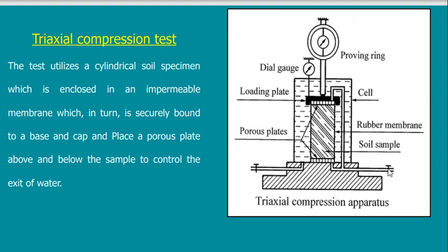If I close this tap, water will not leave. So this tap controls what we said, the permeability. If I close this tap, then it resembles clay with very low permeability, because water is not allowed to leave. If I open the tap, it resembles sand, because water can leave anytime it wants. So opening this tap means that water is free to leave the sample anytime.